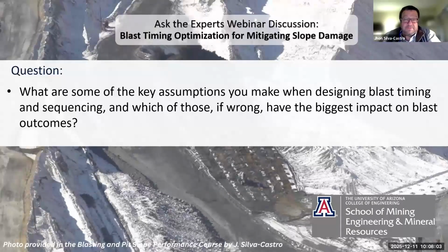Yeah, first, the timing design needs to set what you want to answer. Do you want to control vibrations? Do you want to improve fragmentation? Still, we have not found the secret formula to bring together both fragmentation and vibrations. So sometimes you need to sacrifice one over the other depending on what you want, the angle. However, assuming that your timing is set, definitely the